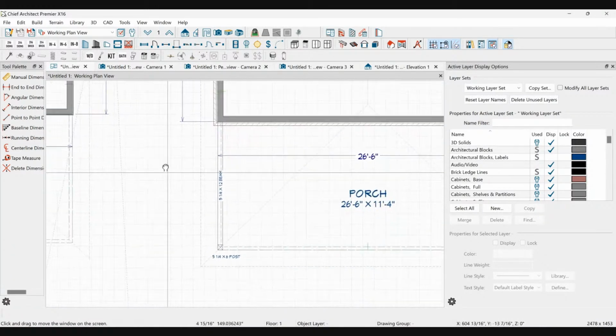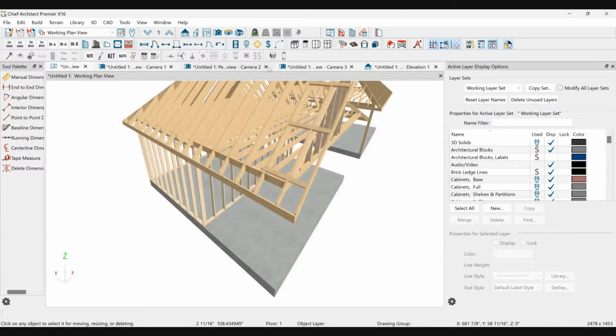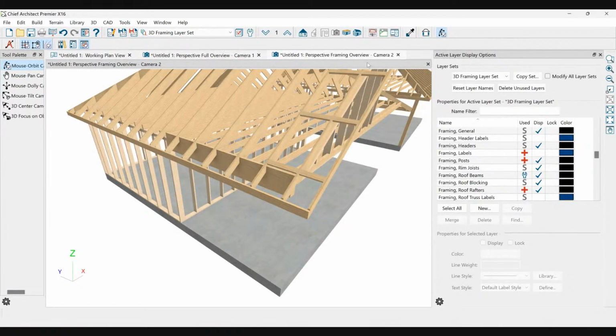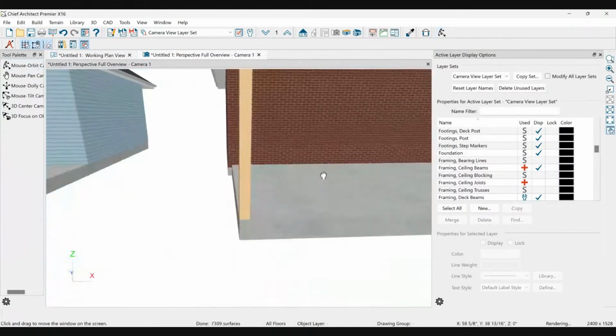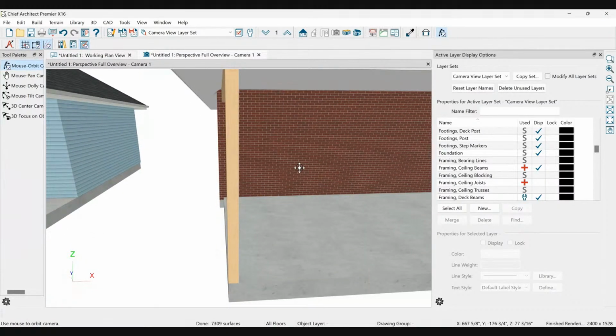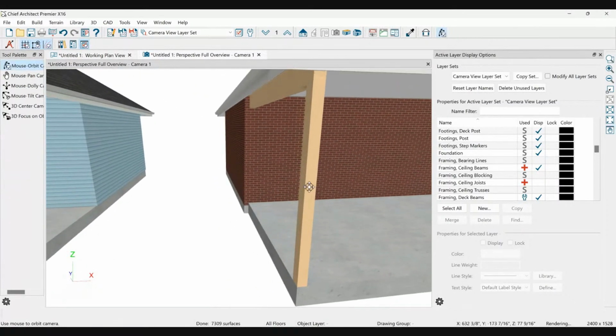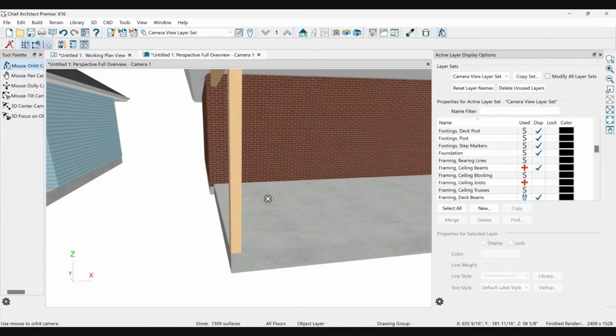Everything's in line. But over here on this house, if we go to the overview and take a look at what this guy's doing, you will notice here's the beam thing going on up here, and the brick needs a lug, right? It needs to sit on something. So the framing is in line, but the slab sticks out where the brick is because the brick sits outside the framing. And so what most people do, or at least what I do in most cases that makes this all look nice and clean, is I say, oh, okay, there's just my slab, I'm just going to extend my slab.